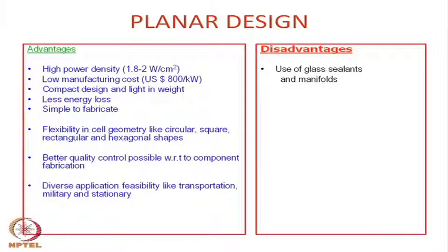In a tubular configuration, it is quite easy, whereas in a planar configuration it is not that easy. So, you need to separate these two chambers, the fuel chamber and the oxidant chamber or the air chamber, through some sealant, a high temperature sealant, and the only option we have is a high temperature glass.